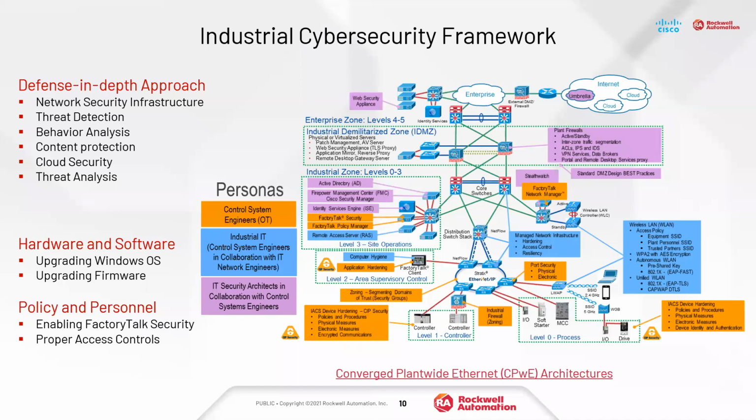And then one big document that we released recently as part of PlantPAx 5.0 on the DCS side, we came out with what's called the Configuration and Implementation User Manual. That provides a system security checklist as part of the documentation so that we can support one of the industrial security standards. So the IEC 62443, there's a 3-3 component that deals with the infrastructure and the architecture.